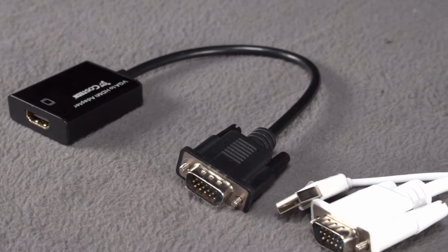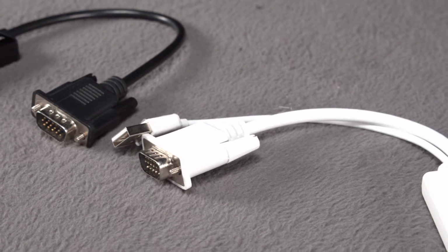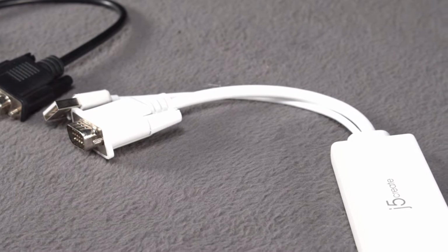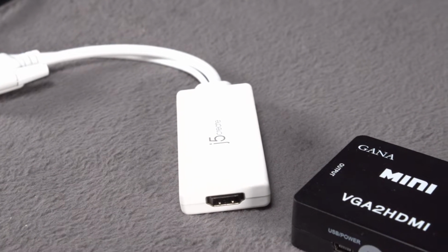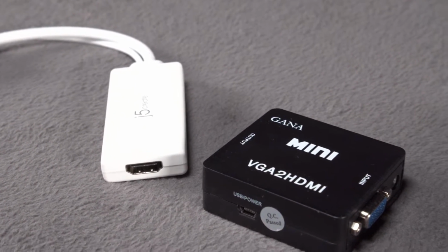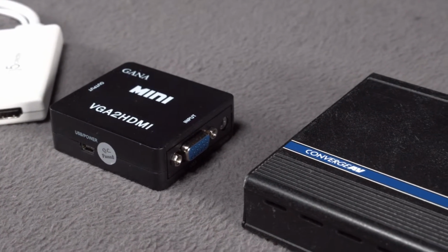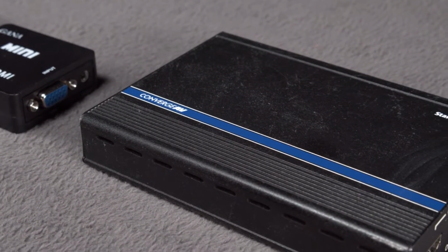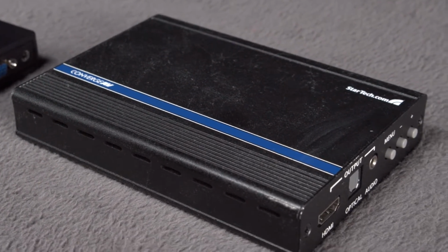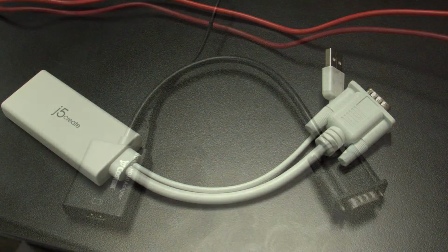Specifically, it was a small and simple VGA to HDMI converter we were using. We followed our suspicions about the converter and replaced it with a different model. Still no success. So we tried yet another model. And as it turns out, the problem is that simple, low-cost converters work well when sending a signal to a modern consumer TV, but they don't have the color depth scanning and frame rate conversion capabilities required for our specific output requirements. We shelved the tiny little converter boxes and picked up a StarTech converter AV,